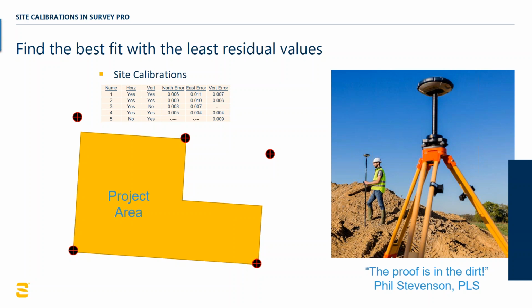The points that I'm using are boundary to my project area. That means that any amount of error that I've got in these points will be interpolated to 0 at the center. So as I approach the center of my project area, theoretically, all of my error disappears. That indirectly infers that maybe my control points should be a lot further away from my project area to help me develop that plane, that vertical and horizontal dimensioning that I'm looking for.